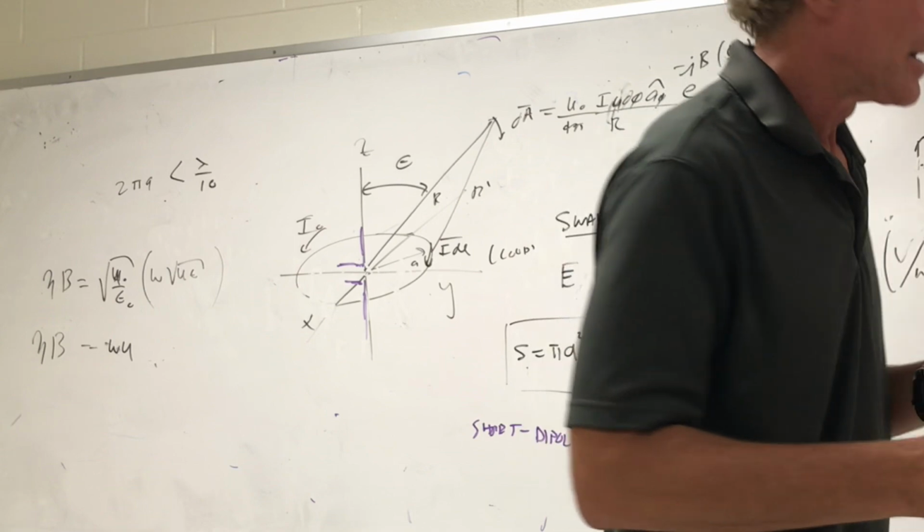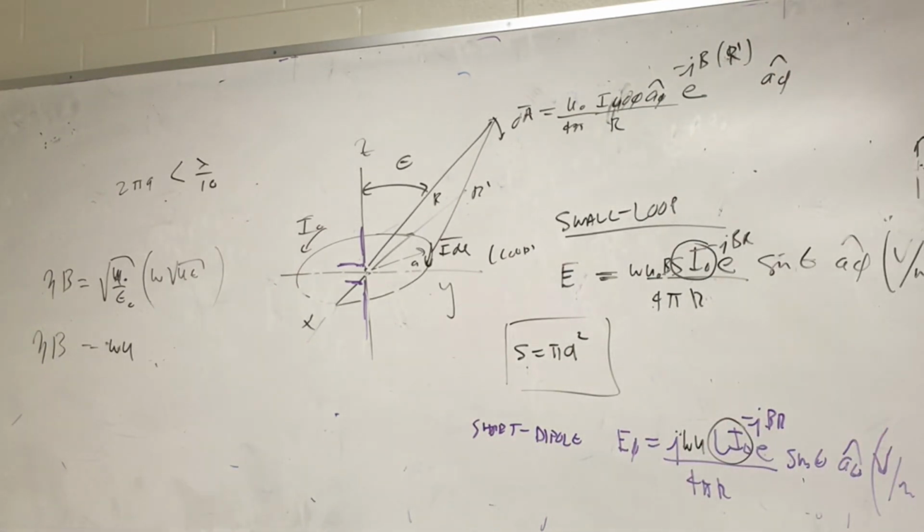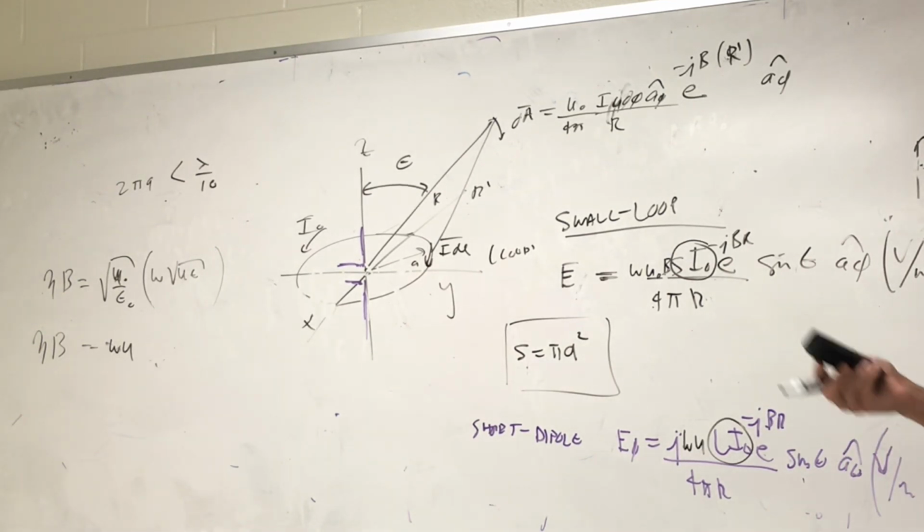All right, now, that's the electric field. How do you get the power density if you needed it? Anyone? Far field power density. 1/2 E naught squared over eta, that's right. Y'all with me? That's what I always do.